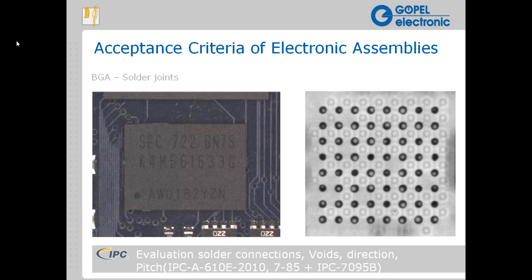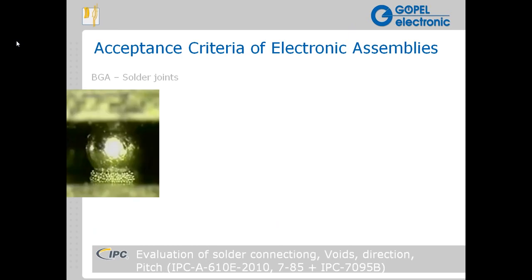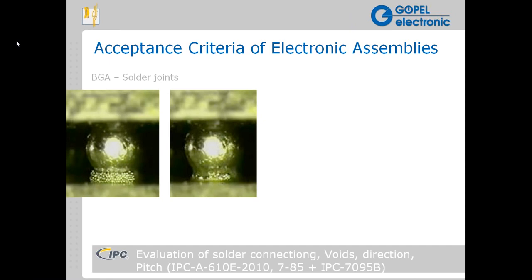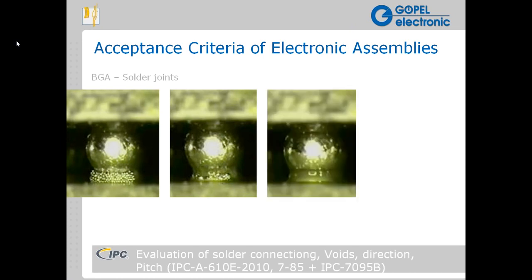So if we look at some of these aspects in the X-ray domain, we won't go into a lot of detail here because frankly there is a lot of detail and complexity involved in BGA inspection. But just to give you a sense of how this all works, we detect the ball basically through its shape. We measure a number of different values: the area of the ball, the compactness, the axis ratio of the ball, the mean gray value of the ball, as well as the mean gray value of the background. So this gives us the ability to characterize a solder ball in situ.